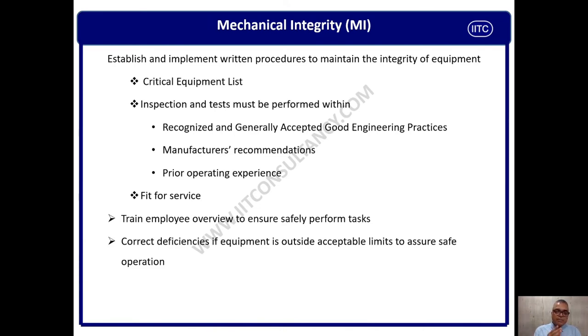Guys, to identify safety critical equipment, health critical equipment, environment critical equipment, there is a system which is called a barrier model. You need to qualify all the equipment as per the barrier model, like prevention, mitigation, isolation, control, PPE, discipline. These are the barrier model questions, and you need to qualify and identify these critical equipment as per these questions. I have prepared a small presentation on how to do and how to identify safety critical elements on the IITC channel. You may feel free to go for that program.